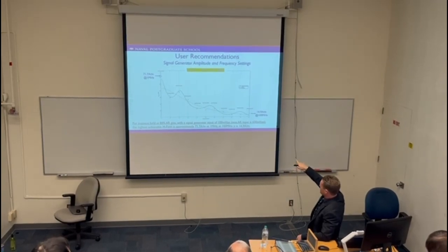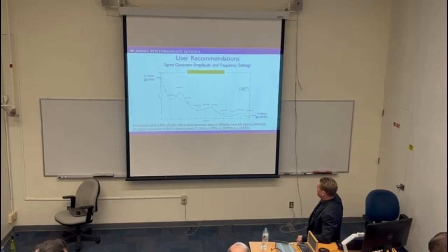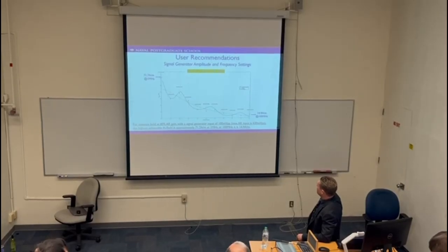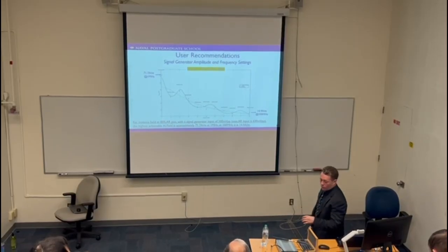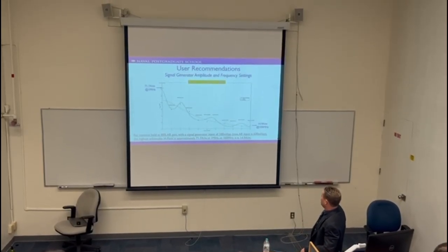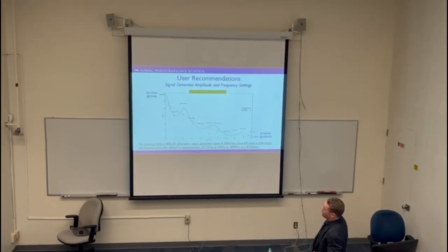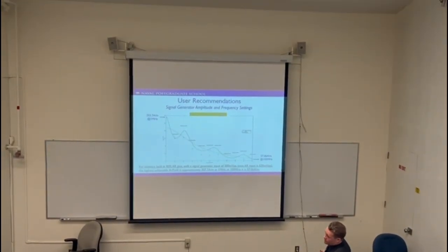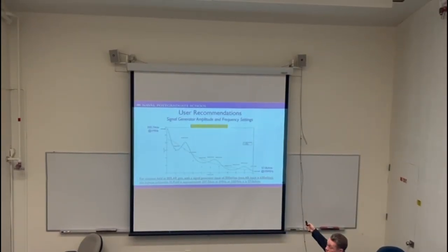And you can see here, the measure points in the little blue dots here in my model, very nicely overlapping again. And I can tell you, again, at say 1 megahertz, that I'm about 71.7 amps per meter in H-field. And at 100 megahertz, I'm about 15 amps per meter. And that was at 100, so then I went up to 500. Remember, the max is 630 millivolts peak to peak. I'm holding my AR constant at 80%.